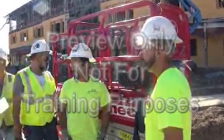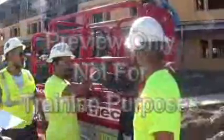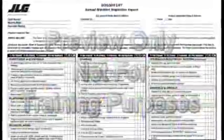Annual inspections must be performed by a qualified person no later than 13 months from the date of the prior annual inspection. The inspection must include all items checked on the frequent inspection and items specified by the manufacturer for an annual inspection, including any manufacturer's bulletins. The MEWP should not be put into service until all malfunctions or problems found during the inspection have been corrected. Documentation, which includes the date and inspection intervals, must be maintained on the MEWP.